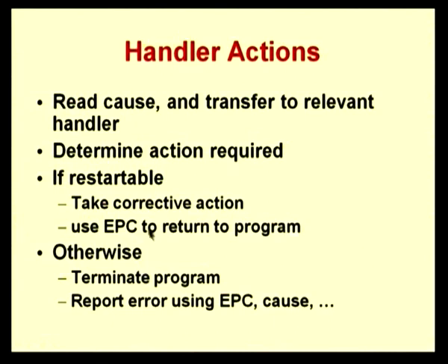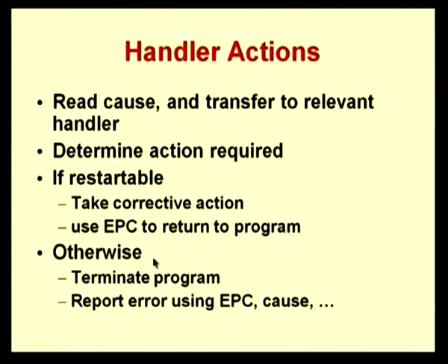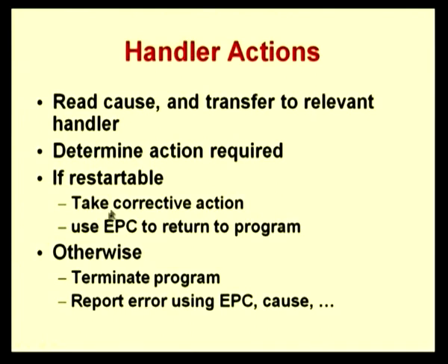Okay. What do I mean by restartable? With some interrupts and some exceptions, when they occur, you don't want to terminate your program. You want to continue with the execution. So you always have to determine whether it is a restartable type of exception or a terminate type of exception. If it is a restart type of exception, then we will restart execution. To do the restart, we have to store the original PC in some location, normally in some special register, and then restart execution from this stage. Okay. So these are additional things that we will have to handle when we deal with exceptions and interrupts. And these make pipelining even more complex.